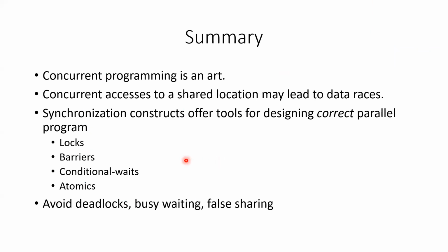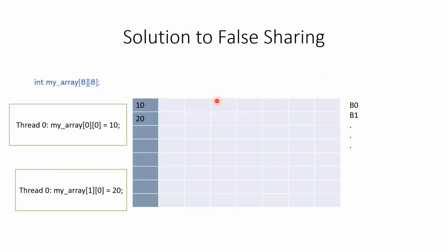My intention is, instead of going for the two-dimensional layout with the padding, which is memory wastage, right? With the existing memory, can we do a ping-pong mechanism? What do you mean by ping-pong? Suppose I have 256 kilobit, I can divide it as 128 kilobit and 128 kilobit. Array 0 should go into the first ping buffer, and then array 1 will go to the pong buffer while writing. Does that work in the threads concept? I was not able to follow what the solution is.